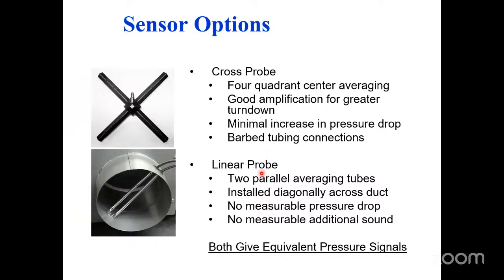All right, I mentioned earlier there's a cross flow on the inlet of the primary air from the air handler to the VAV box. That is so the VAV box controller can measure, specifically, velocity pressure and static pressure, and it uses that along with you telling it at programming time what the dimensional opening is to calculate how much CFM it is moving.